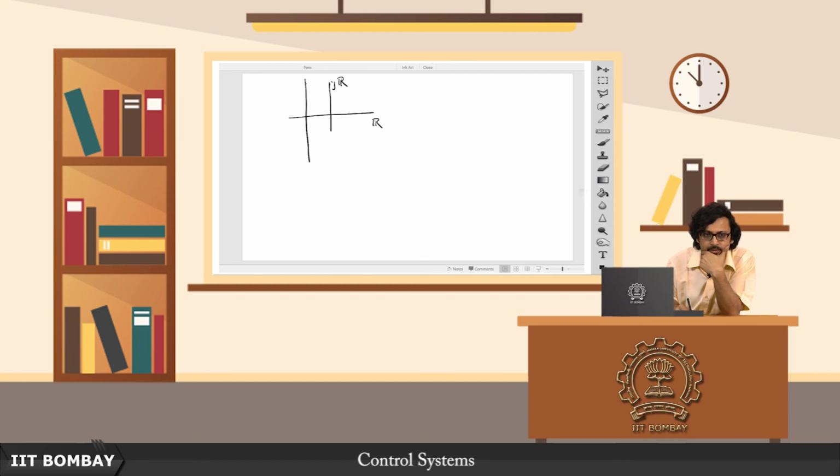So again, to refresh, notice that this pole pair marked in red and this pole pair marked in green are different, they are distinct poles no doubt, but both these pairs, the red and green pairs, share the same real part. And by virtue of sharing the same real part, they also give rise to the same value of settling time, albeit approximate, let us not forget that. But once we agreed upon the fact that this is going to be our settling time, we know that this